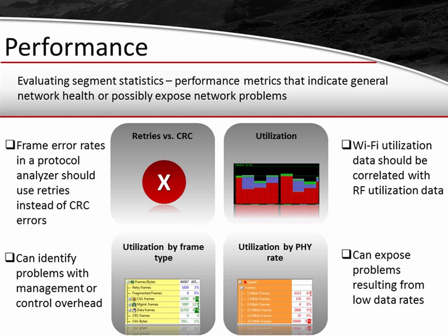And the reason for that is sometimes a retry will occur and there is no CRC error because there is no frame that was received at all. The frame can be totally discarded and not really received. So if we're only looking at CRCs, we may not get the full picture. But if we see that there's a retry of 3 times before the frame gets through, we know something happened to keep that frame from getting through the other times. So retry rates are important.